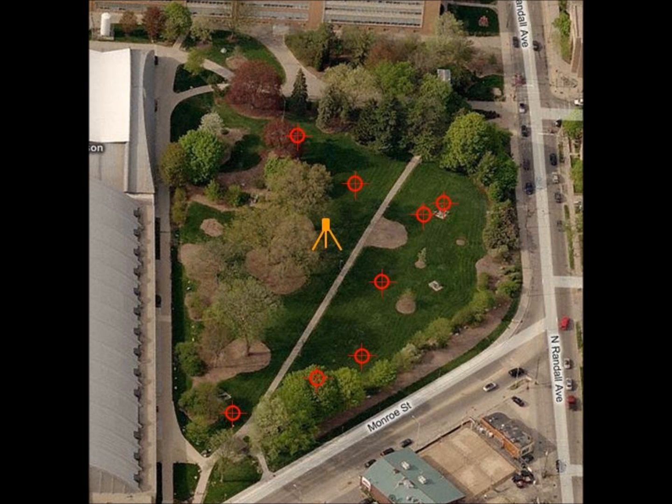First, you'll need to set up a total station in a location where you can get a clear shot of at least 2 control points and also get a good view of the hill. Follow the instructions of the previous video on total station setup. Make sure you print out the lab instructions so that you know how to operate the total station.